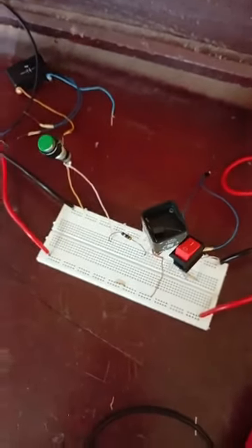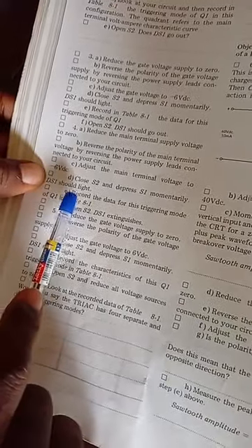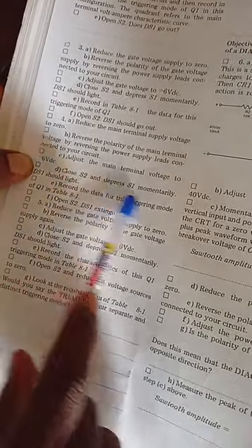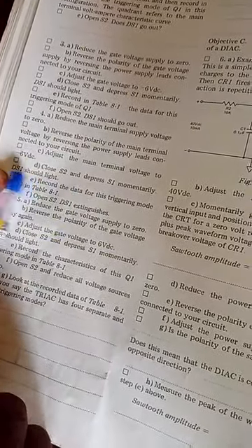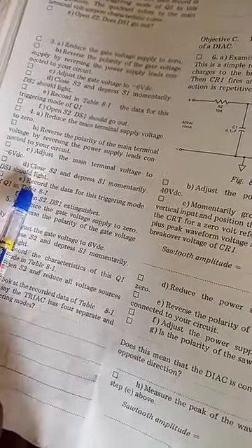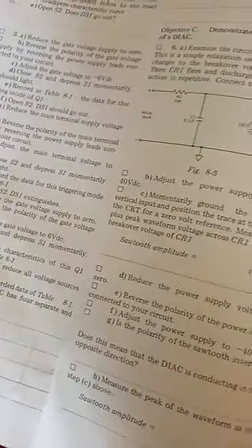So at the third quadrant, you can see that we reversed the polarity. We have done that. Then adjust the terminal output to 6 volts. We have 6 volts already. Close switch 1 and depress; we've done that. We depress and DS should light, and it lit. Record data for what we have in our third quadrant. Negative main terminal polarity, that's the AC source, and negative DC source.